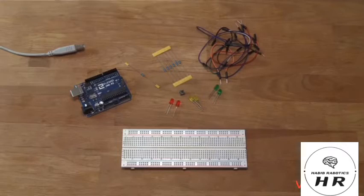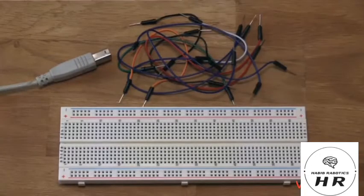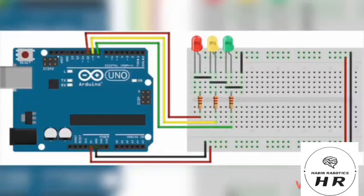We need one 10 kilo ohm resistor, six 220 ohm resistors, one push button, and of course our traffic lights, namely 2 red LEDs, 2 yellow LEDs, and 2 green LEDs. You're also going to need a breadboard and some hookup wires, along with a USB cable to attach the Arduino to your computer. Let's start by setting up a basic Arduino traffic light circuit.